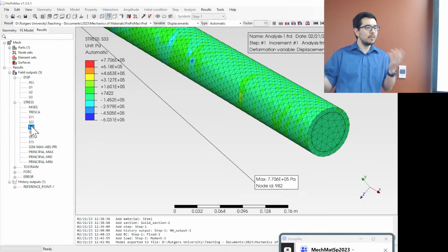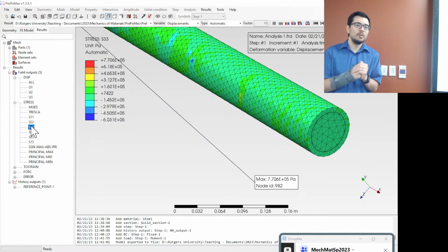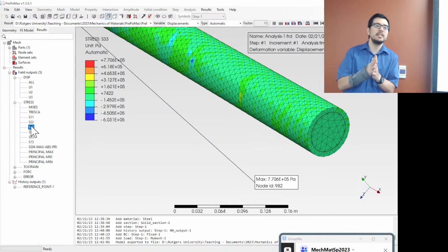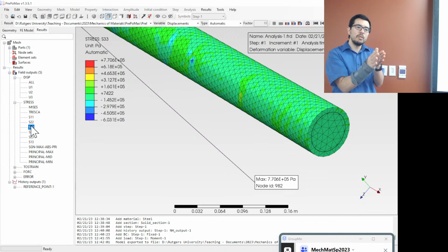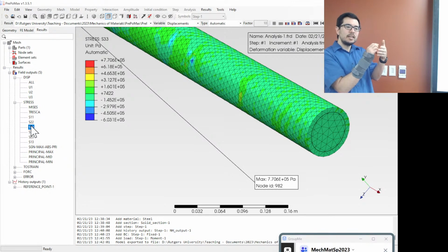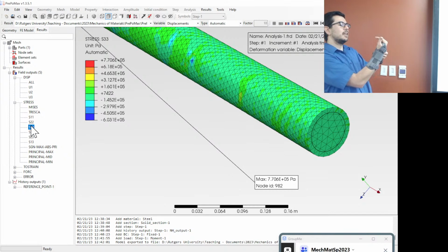So that leaves the 1, 2, 1, 3, 2, 3. When we think of shear stresses and we take a cut and we're looking at the cut, and this is coming off a particular axis, which face are we looking at? We're looking at the one face, right? We're looking at the X face. So I'm looking at the one face, it's looking at me, and I want shear stress. So which components am I going to be interested in?